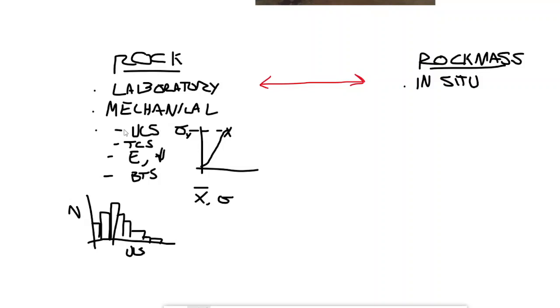And you could go in and look at the literature and say, well, maybe you pluck out the UCS would be a great one. The TCS would be another good one. The strengthening factors, maybe how well it holds up under confinement, shear strength factors. You could look at these and say, well, on average, it's this, and the spread of the data tends to be this. So we should accommodate the worst case scenario, and maybe account for the lowest area, maybe develop a confidence interval, right? You could go back to simple scientific and mathematical processes to make an informed decision about the rock.